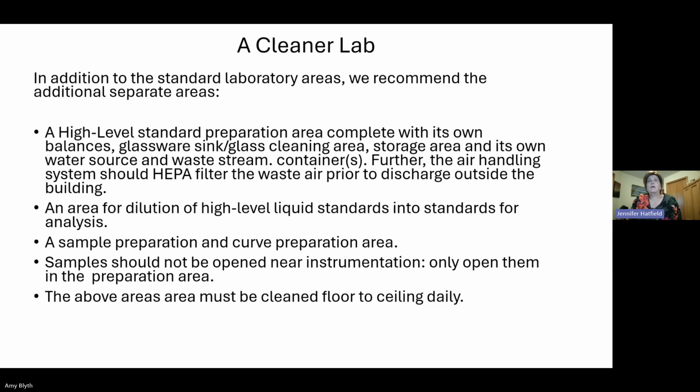In addition to clean water, we needed a cleaner lab, and this is kind of where we set up. And the reason it started is one person had the high level standard of the potassium salt of PFOS. They would come trotting through the lab, and it went poof, and we contaminated the entire lab. And because of our air handling system and the way it was working, samples got contaminated. It was a mess. We ended up having to clean a lot of stuff that we never thought we would clean. And after that, we put in an area that would be for high level standard sample prep.